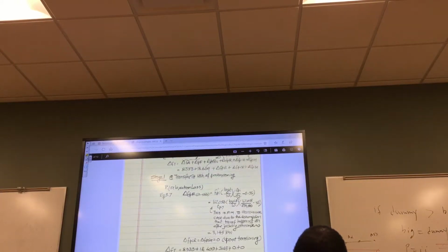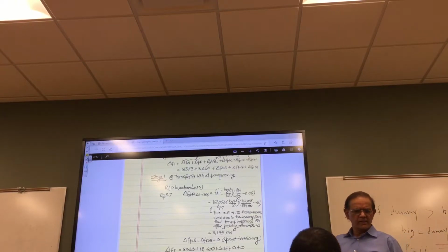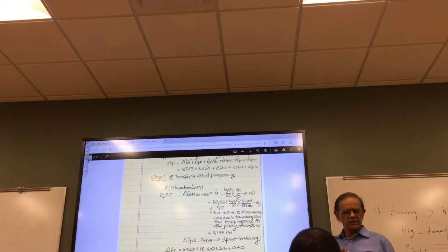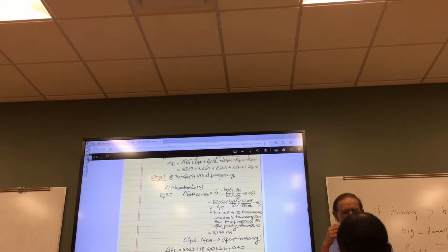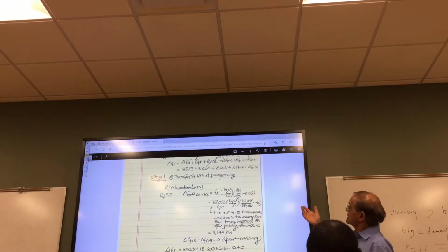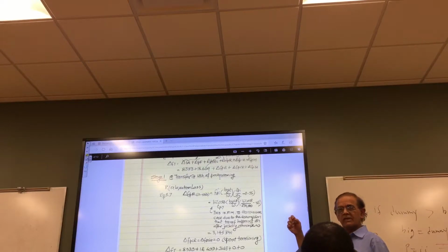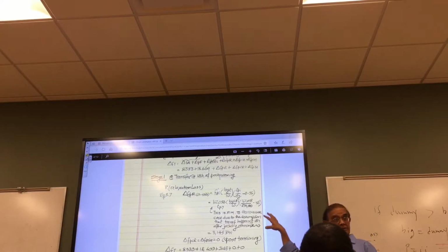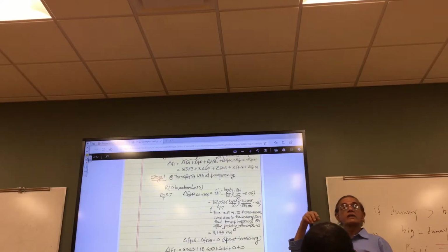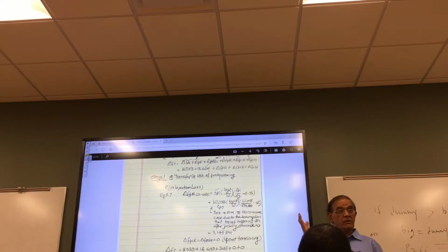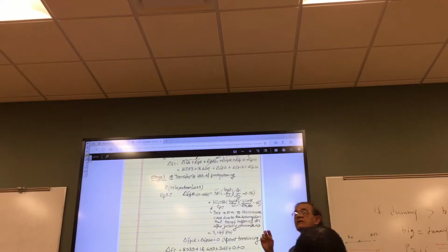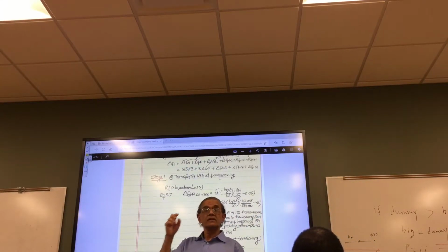And we go through stage 1, which is transfer of pre-stressing at 18 hours. Right? In the last assignment you got, I had asked you to do it in stages, or the step-by-step method. But we didn't say what time the pre-stress transfer is happening. So when I did the example in class, I showed you can back calculate your timing based on the strength of concrete. Remember we had a formula that involves alpha and beta to calculate, if you know the time, you can calculate the strength.